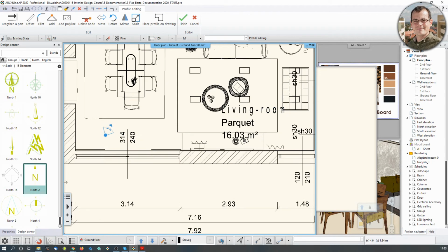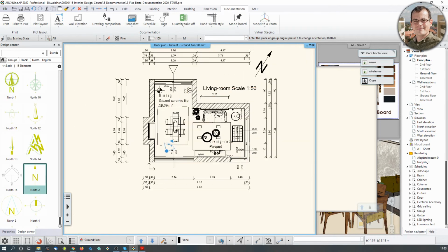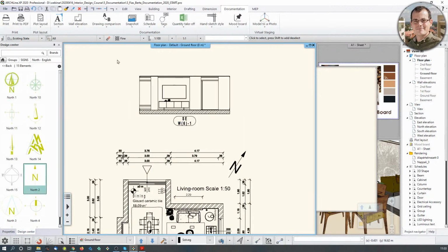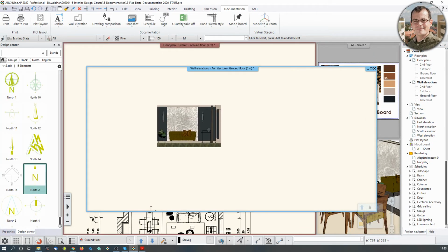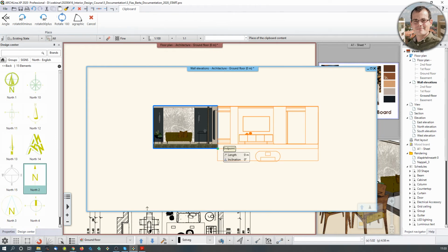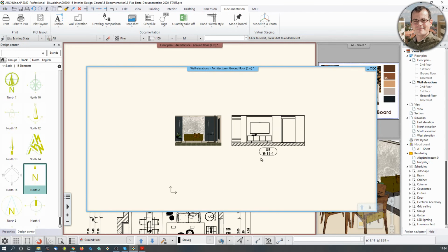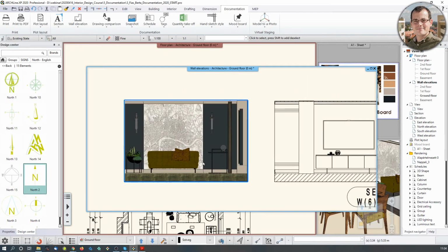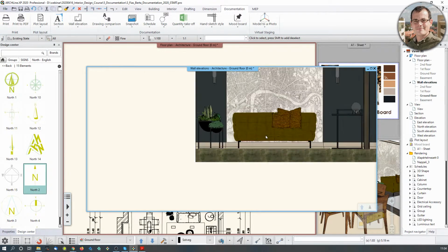Do I want to trim it back? No, I think this is fine. Hit enter, and now I ended up with another drawing. So if I highlight it, Ctrl X, it's better to collect them separately, because that way your design would be much cleaner. So let me show you how to dimension onto these documents, because even though this looks like a picture, it's still got nodes onto which you can dimension things.